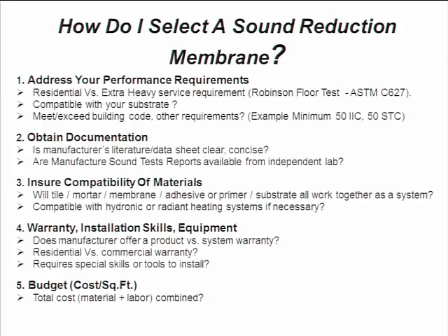This is one that I would recommend: obtain documentation from your manufacturer of your sound control membrane. Get a copy of their actual test report, because many of the brochures are marketing related. You want to show your system in the best light, you want to show the best number, but if they don't have the details on how that number was arrived at, it is rather pointless.